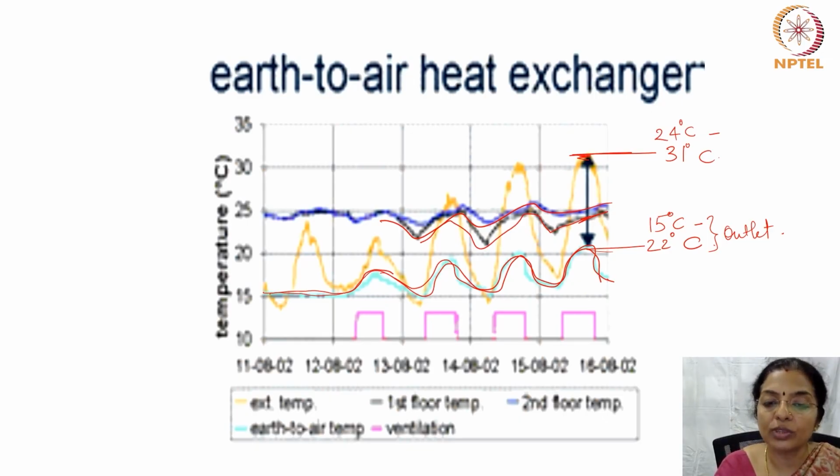This can be the impact of earth air tunnels, and you can see how much energy savings can happen, because the load on the air conditioner will be completely cut sometimes, and sometimes it can be dramatically reduced because the air temperature that the air conditioner has to handle is much less than the outside air temperature.